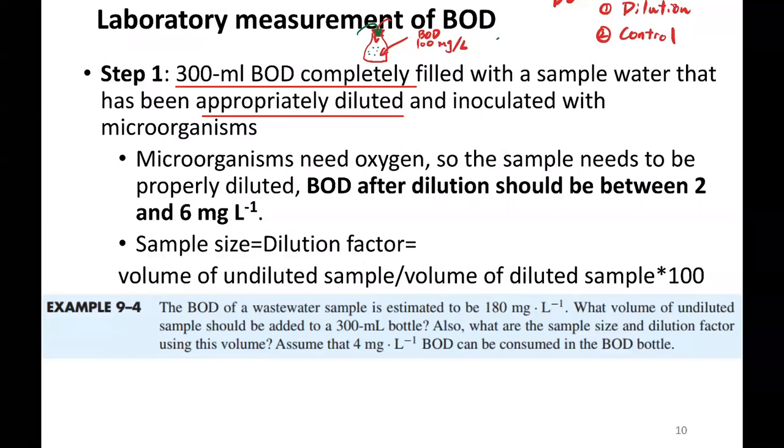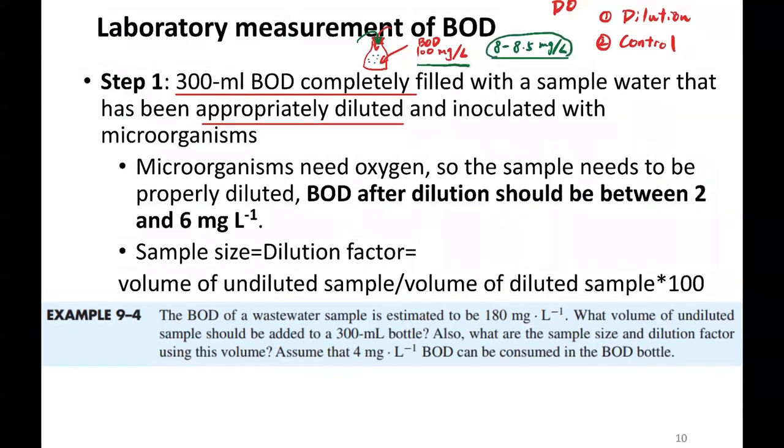So what this means is that we have so much organic waste inside, and the maximum difference of the dissolved oxygen is just going to be this amount, right? Let's say if we wait for 1 year or several years, then the dissolved oxygen will always be 0. In the beginning, it's maybe around 8 to 8.5, but finally it's always going to be 0, mainly because there is no more oxygen in the water anymore.